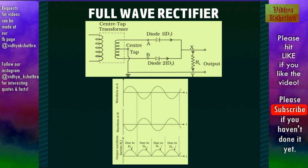When B is positive, D2 becomes forward biased and D1 becomes reverse biased. Then we get the output voltage through D2 and then the load resistor R. And the output voltages are shown in these graphs.